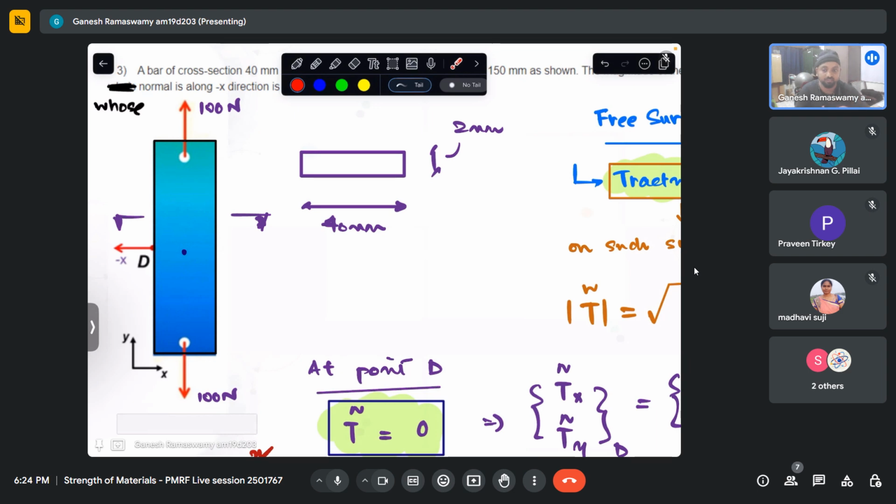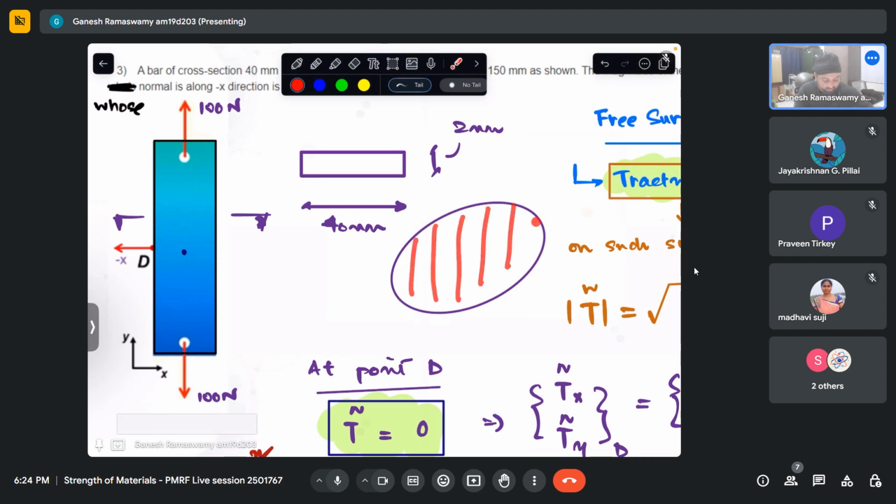Given that this was a simple problem, you were able to deduce it quickly because it is a uniaxial tension. But in the case of normal three-dimensional problems, we will have a surface, we will have a domain, and we don't know how the stresses are distributed inside the body. So we will be defining the boundary conditions, how our displacements and tractions are defined on these boundaries. And there will be governing equations which take care of the distribution, which will be the output of your analysis.